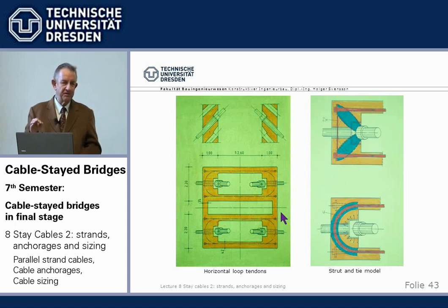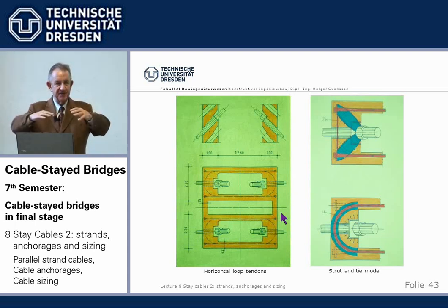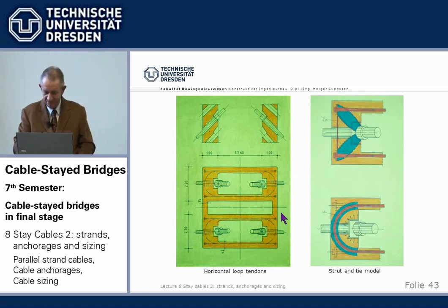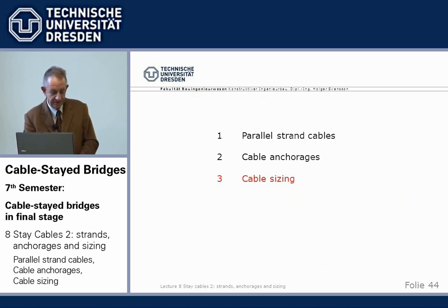Although it's a very good system, it's not much used today. Instead the steel pad is used, cast in, and don't fiddle around with the tendons. That's how practical use sometimes overcomes the good theoretical solution.